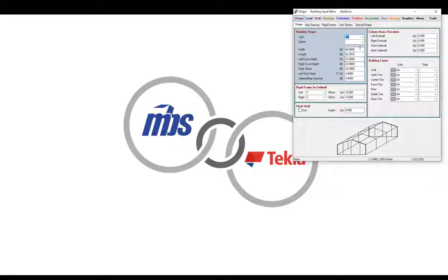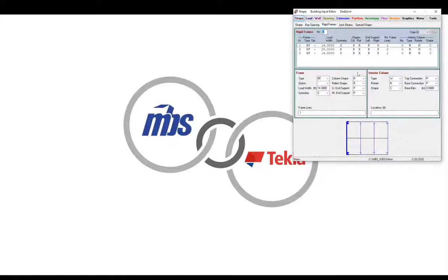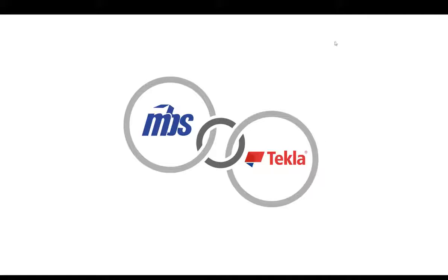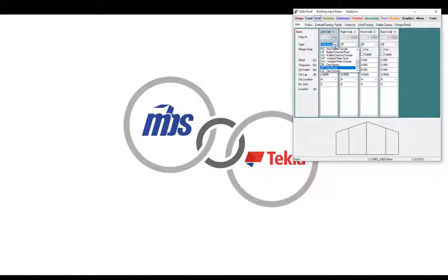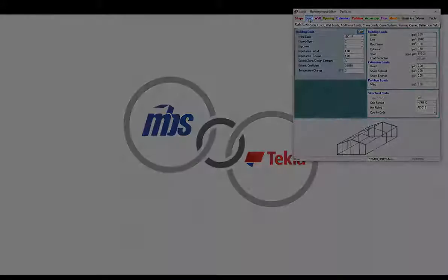This example of the main part of our building includes the width and the height, our eave heights and roof slopes. You can also enter things like your column base elevations. In here we can define the base spacings, we can define rigid frame locations and types. You can also define things like openings, you can define your roof purlins, your wall girts, types, spaces, and then finally we can apply the loads using your local building codes.